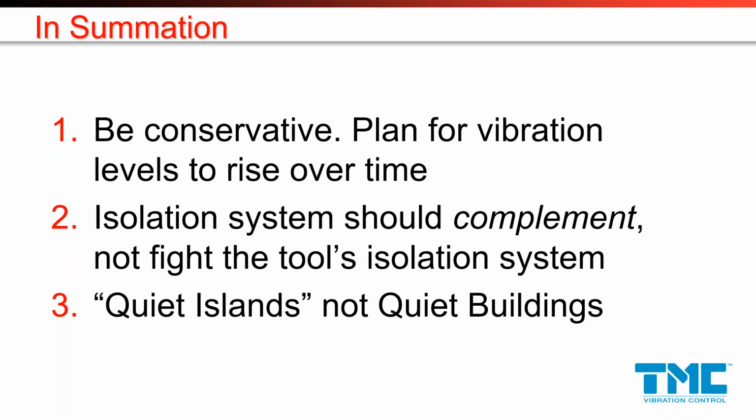So the first one is, if I don't know the exact tool set that will be installed, is there a design protocol I should follow to allow future installation of quiet islands that may or may not require active isolation? Well, that would be the third case study we talked about for Oregon Health Sciences University. What we'd consider best practices would be designing around having a raised access floor, say 18 inches or 24 inches high, over a concrete subfloor, which should be at least 8 to 12 inches thick, adequately supported.